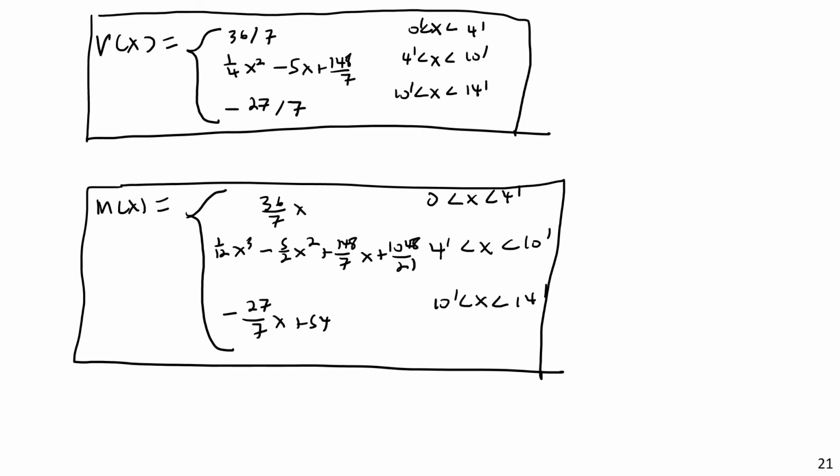Because often what you're looking for in beam design is location of maximum shear. Typically you want the max shear and the max moment. And once you have the equations, then you can just apply basic principles of calculus to solve for points of maximum, or you can plot them on a calculator, or whatever you may wish to do.